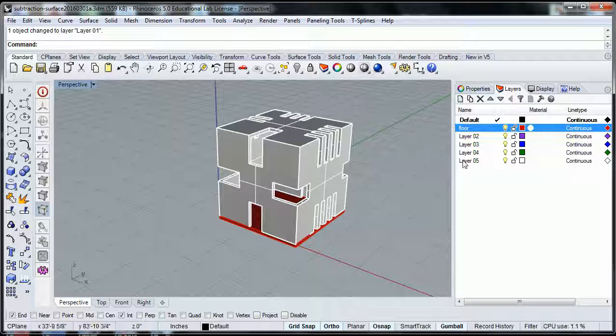So layer 5, which will move the walls and stuff, let's change that to shell. Okay, so shell. All right, and I have that highlighted right now. I kind of purposely put the shell at the very bottom here at layer 5. If I don't like the order that these are in, you could come up to this little triangle. It's kind of like an elevator triangle, right? If you click on that, that layer would move up. I'm going to move it up above the floor because that makes a little bit more sense. Shell and then floor. Okay? You could always move it down or move it up, whichever.